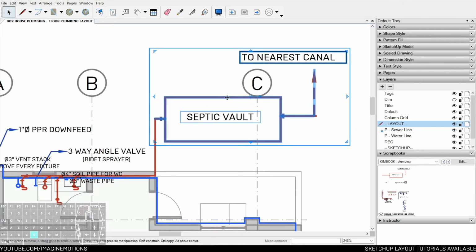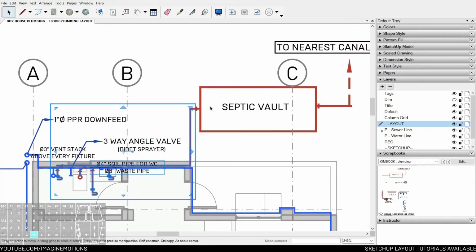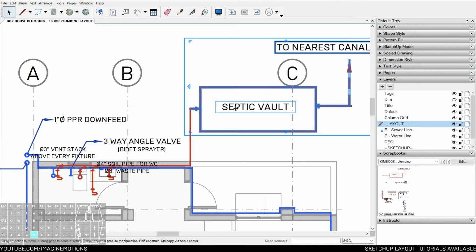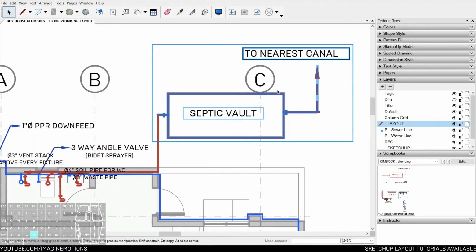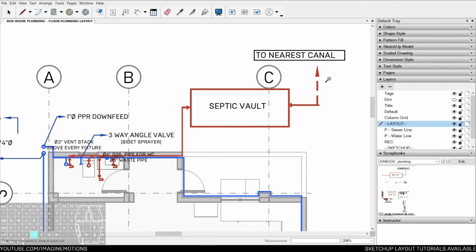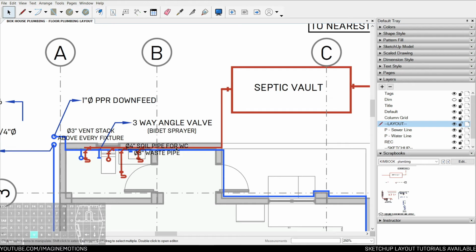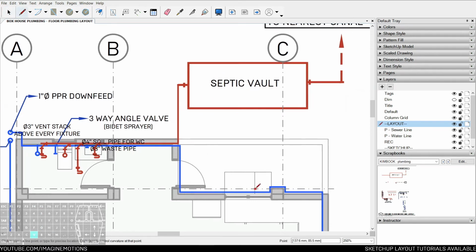So this will be in a callout for our digestive chamber and our leaching chamber. This is mainly for our soil pipe, or poop, so that when it gets digested, it leaches. The effluent that comes out is not solid. It comes out as much as possible as just clear water. And then our drainage for laundry could go straight towards the canal.